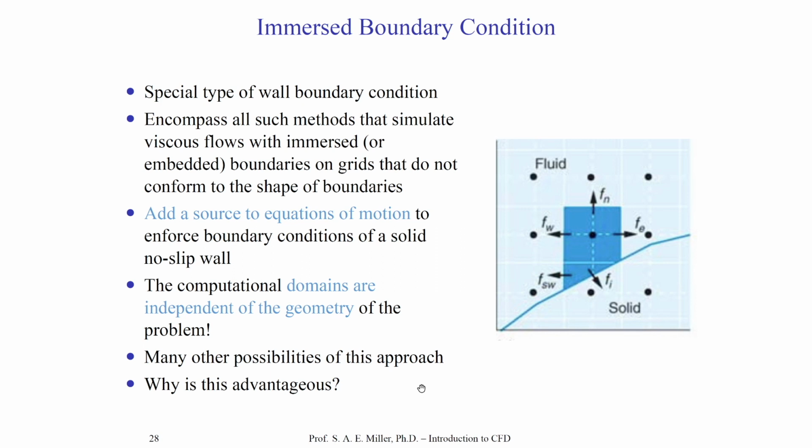This is a very, very difficult boundary condition to implement because now we are solving the same fluid dynamics equations with a modification of inhomogeneous sources along these lines of the wall. And we will have to use the computational power of the solver to find solutions inside the wall and outside. At the end, when we visualize the results and examine them, we would disregard the solid wall grid points. They're only there to enforce no flow through the wall.